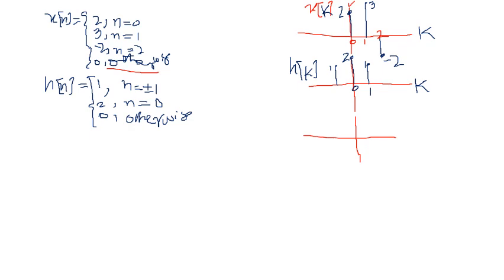So you understand how to reflect. It's something like you put a mirror here, so you see its replica this side. You see the signal is actually symmetric, which means it's an even function of the independent variable. So its reflected version will again be the same as what it has, right? So it looks like this, and this is your h of minus k, right?